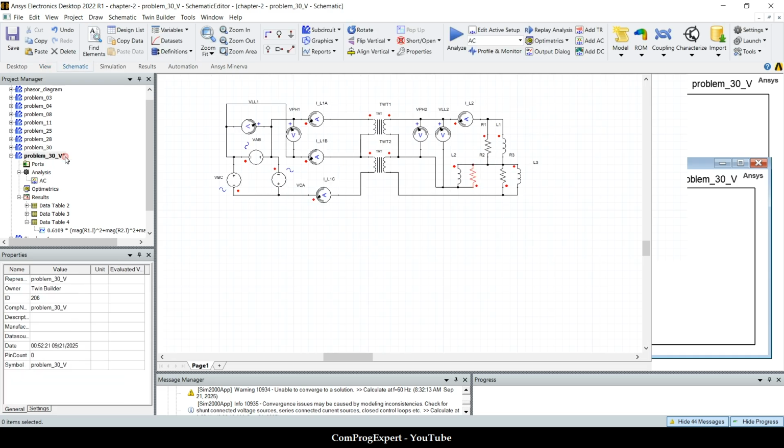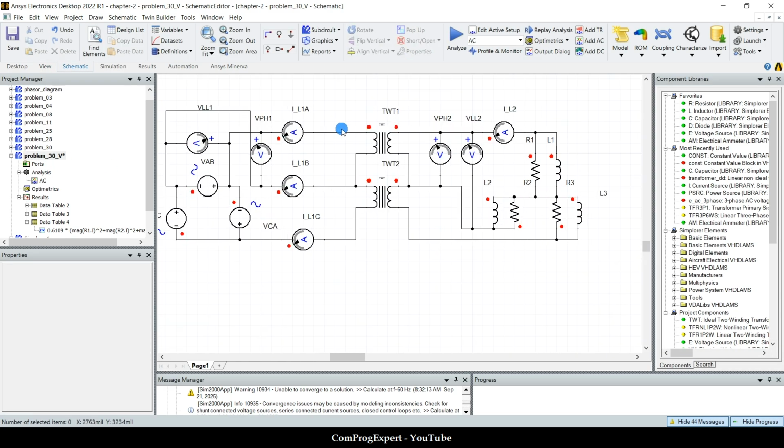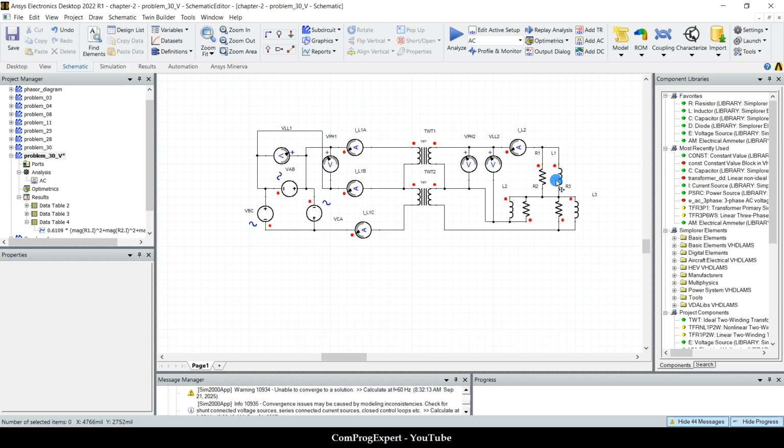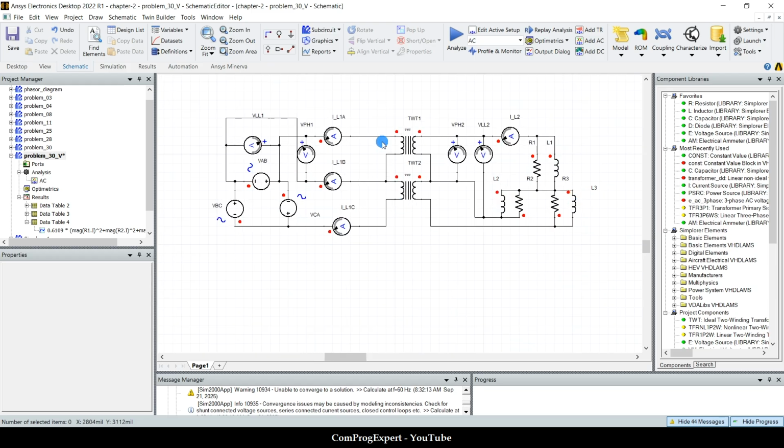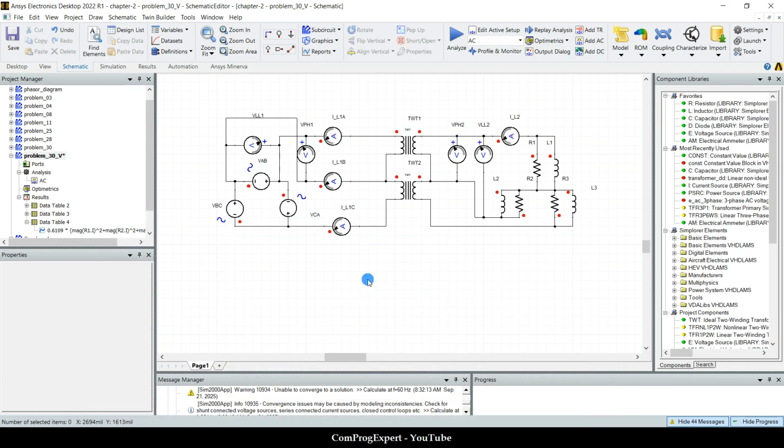Perfect software. We can do these simulations. And as you can see here, in the V case, using only 2 transformers, we can deliver a 3-phase load. You can even measure the values of P1 and P2 separately.